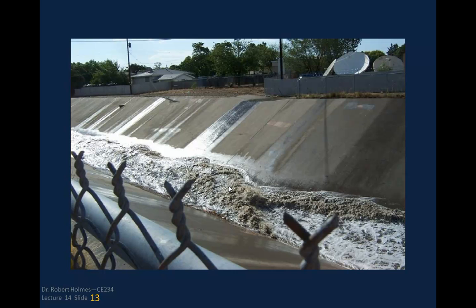I'm getting ready to head to Colorado to work on the floods that occurred there in the Boulder area. And one of the things that we have a problem with identifying after the fact, trying to resurrect the flows from the water surface profiles, is that we can have sections which are supercritical, and then sections a little bit farther downstream that are subcritical, and then it can go back when the slopes change to a supercritical condition. And so you have going from super to sub back to super. It's very difficult to model the hydraulics of these large gradient streams.